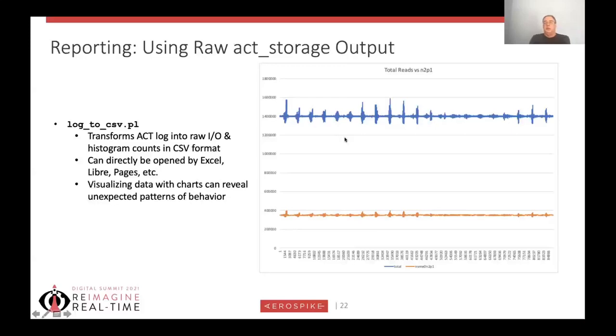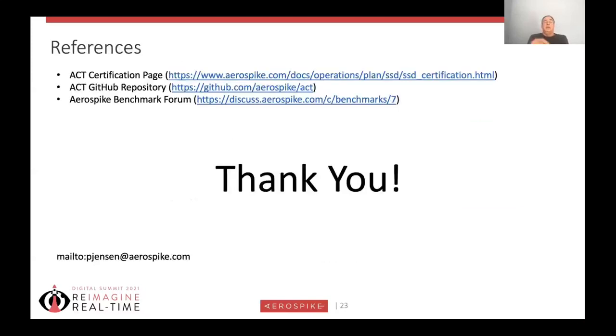This graph on the right is just showing IO rates per second, and you can see those regular spikes. That's an indication probably of garbage collection. When the reads go up, that probably means garbage collection is completed and you have a lot of free pages. So getting a new page for a write is very fast. You don't have to stop and find one. Likewise, if garbage collection is in process, or you don't have a lot of free pages, you can go the other direction. This is the end of the talk.